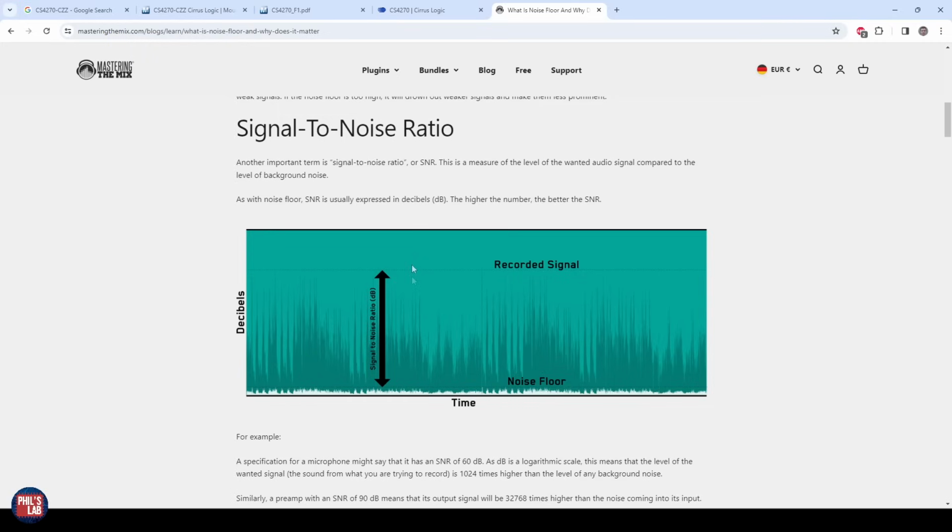Remember, we want a large gap, or large spacing, between our recorded signal, at least in their terminology here, versus the noise floor and any other spurious signals. Noise floors around 80, 90 plus decibels are pretty decent, but you'll see some pretty advanced systems with high dynamic ranges that go over 100, 110 dB dynamic range or signal to noise ratio.